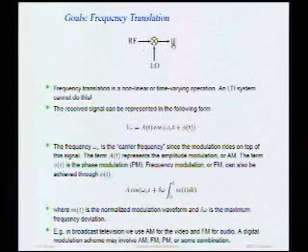We draw them as a circle with an X to emphasize the fact that they're kind of taking a product. Not strictly valid, but it's a good first order approximation. If I take the product of two, let's say, cosines, the output is a cosine at the sum frequency and a cosine at the difference frequency. So certainly products are a way to build mixers. Some terminology, usually for a down conversion system, down conversion meaning we're going down in frequency, like in a receiver, we have an input RF frequency, and generally we have an IF frequency, or intermediate frequency, which is lower. And in order to generate that lower frequency, we use what's called the local oscillator, or the LO frequency.